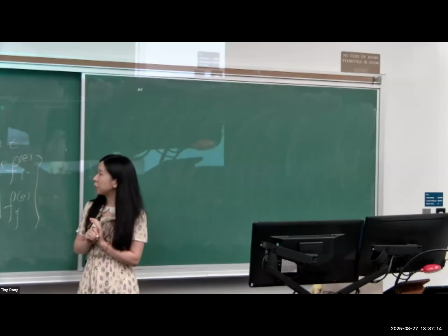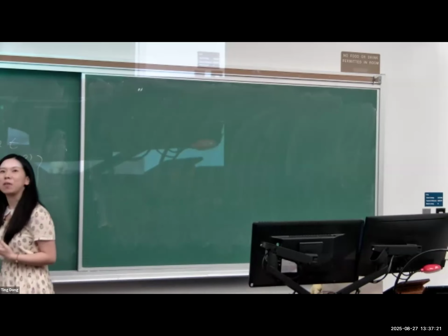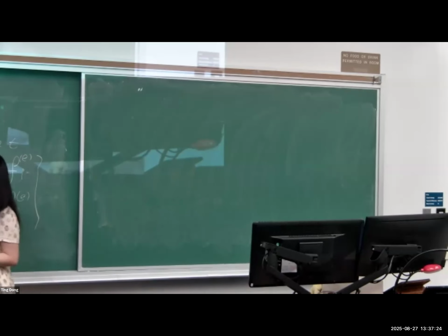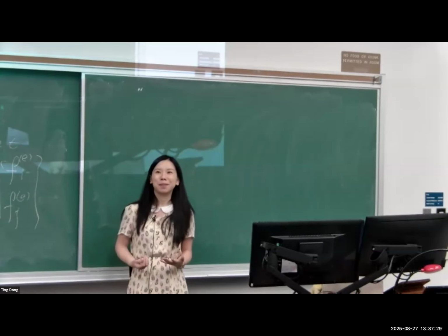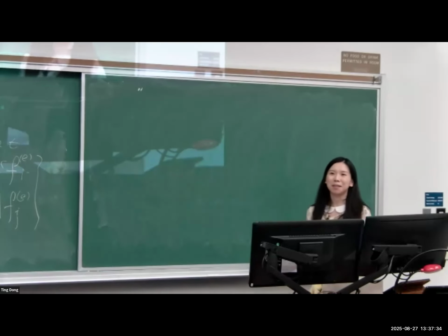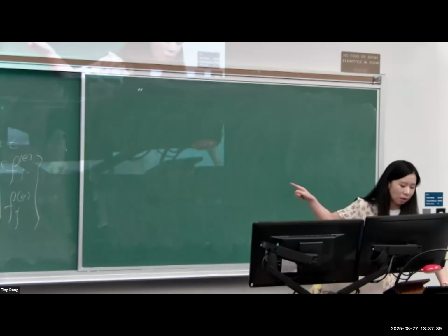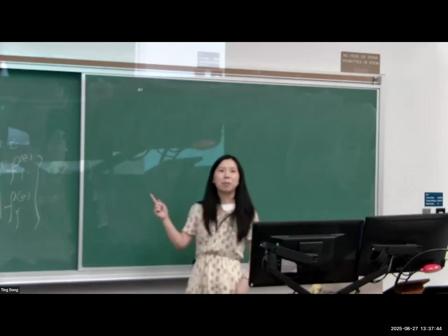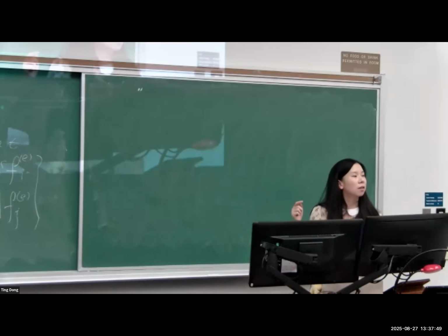And now if you check this matrix equation, you can understand why I said before that all our matrix equations are singular. What's the determinant of this one? 1 times 1 minus 1 times 1, it's 0. We cannot solve it. Anybody know why it's always like this? What does it mean? The physical meaning, this is pure math. The determinant is equal to 0, and we cannot solve for Ui and Uj. Why is that? What's the physical meaning behind it? Constant stiffness.